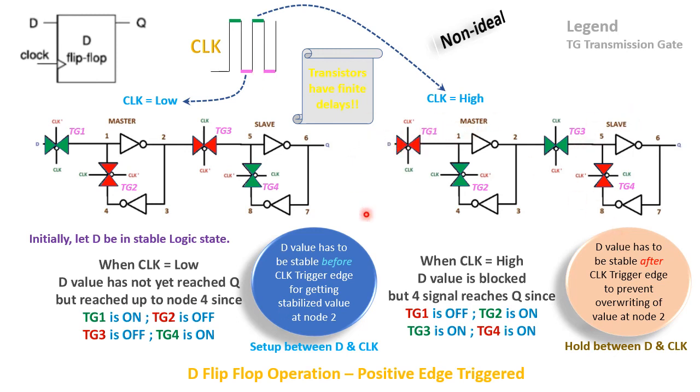Okay, and in the case of setup, we need one more clock cycle by when the data will be modified and the modification will be detected. So that is one reason why setup checking needs one clock cycle and hold checking needs to be done at the same clock edge.